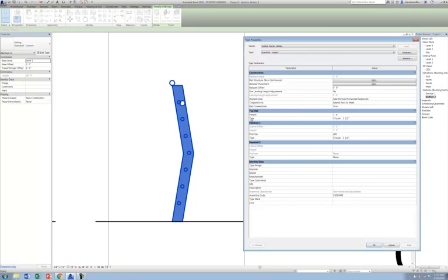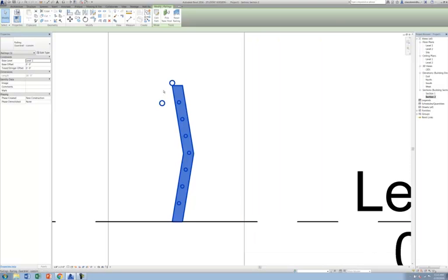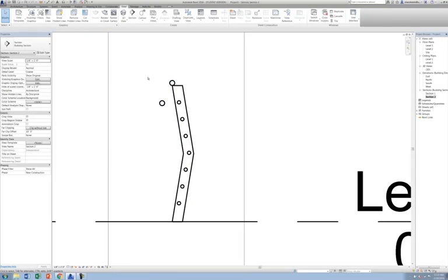So the guardrail is listed here, or excuse me, the handrail is listed here as the kind of custom piece. So this one I actually could just flip. You can see the offset there set to 3 inches and the height set to 3 feet. I'm just going to flip it to right side so that it pops out to that side. Now let's just look at maybe how we could do a custom top rail for this railing.